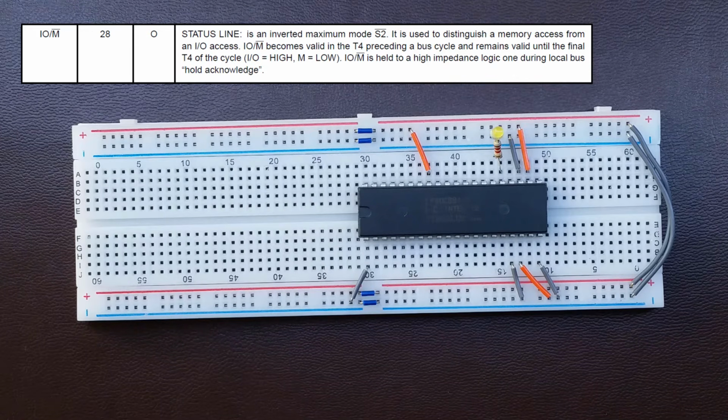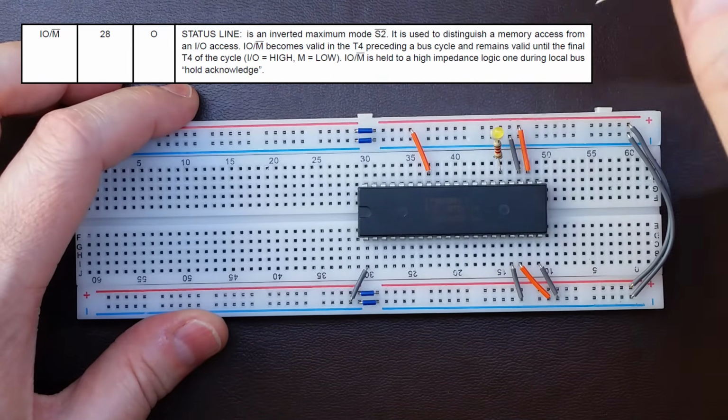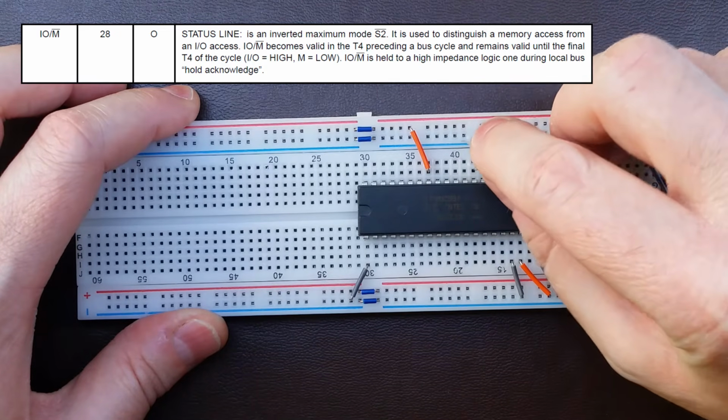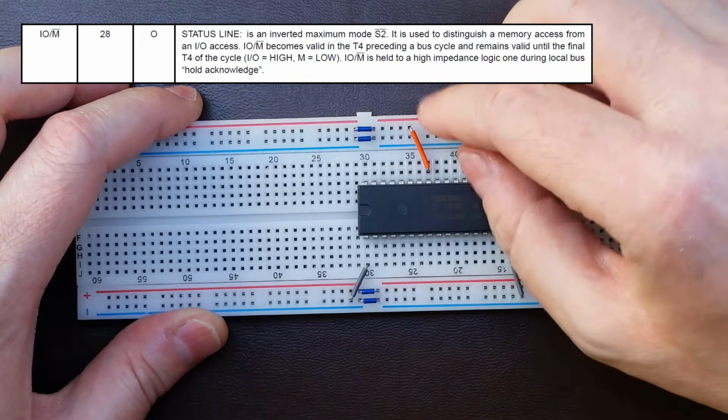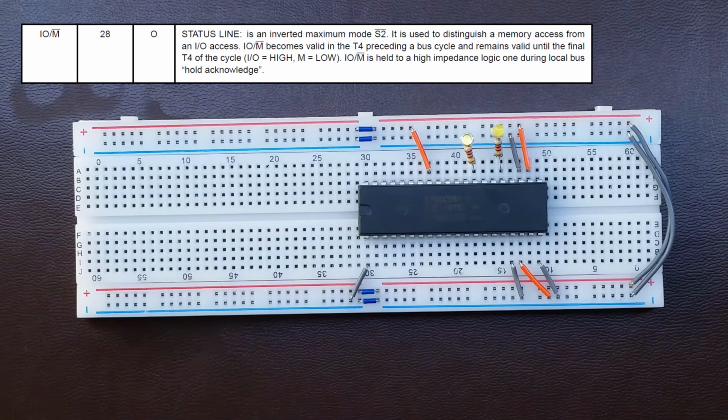It is low for the memory and high for the I/O. In fact, this pin is one of the few differences between the 8088 and 8086. The latter has this pin inverted for some reason. Anyway, I'm going to put an LED between this pin and the ground. It will light up when the processor requests access to the I/O address space. It may be useful in the next video.